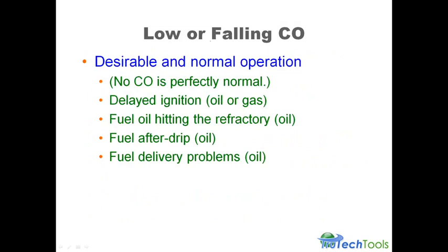A falling CO, that's desirable, right? When the burner lights, the CO should fall. No CO is perfectly normal. Don't panic when you don't see CO. You don't have CO with every combustion process. I've seen tons of gas furnaces and oil furnaces that produce no CO when they're operating properly.